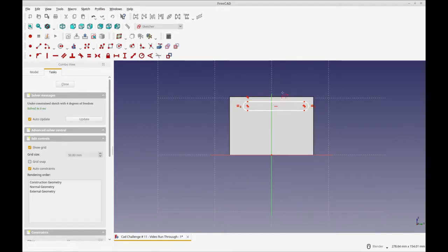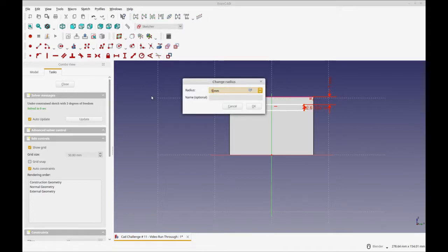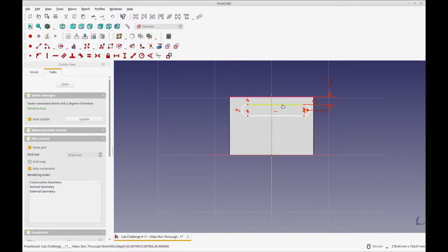The slot is going to be 7 from this external edge and 7 from this external edge. So let's pick the edge, and we can use this point for both of them. In this case, vertical distance is going to be 7. Now we don't have that same vertex to select there, so we're going to use the radius plus 7. This radius is set to 5. That's not explicitly defined, but I found that that's what worked.